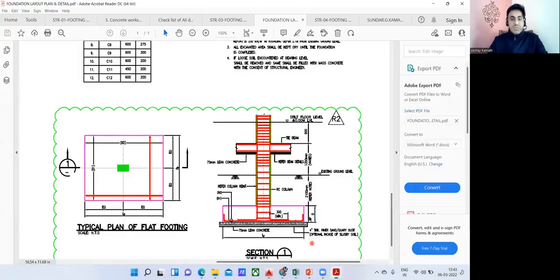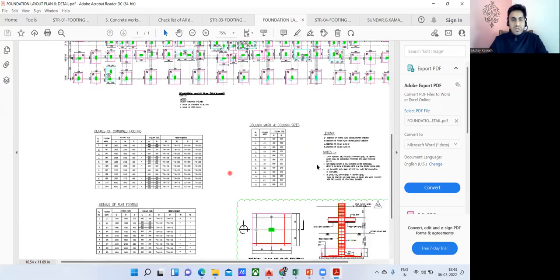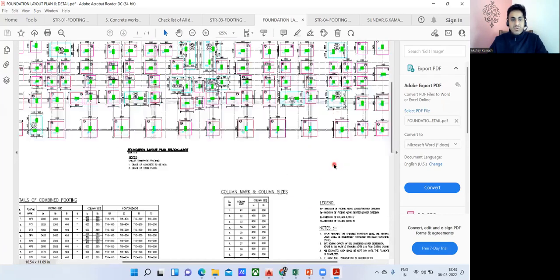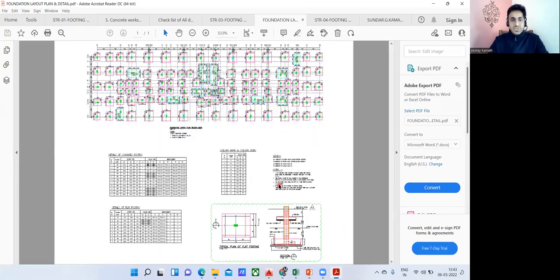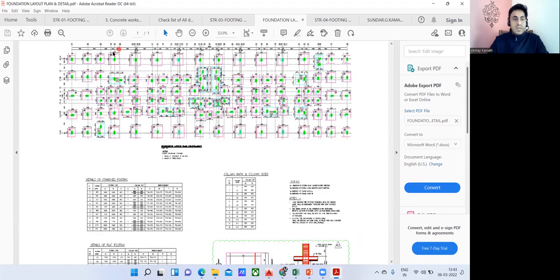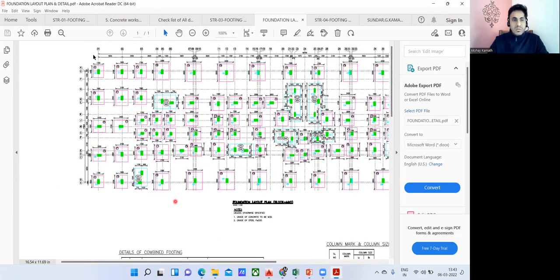Now imagine you have been working, you started to work on this project. Again, you see here how many footings are there? A lot of footings, isn't it? Everything is a footing here. So you can see the footings here. Everywhere it is a footing. So in this way, again, how are you going to plan? What you're supposed to do is, let us say today you are going to do the excavation of these 5 footings. You'll store the soil somewhere here.